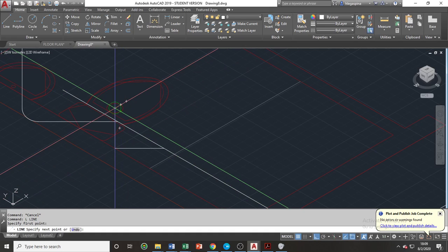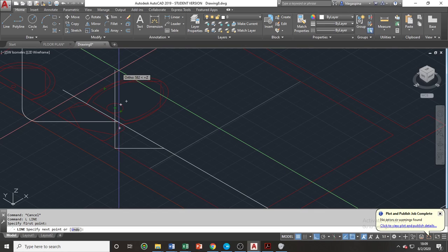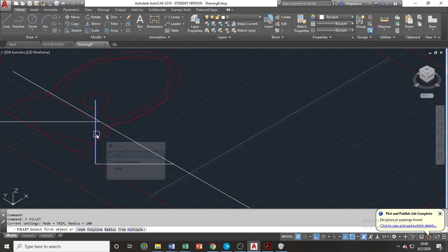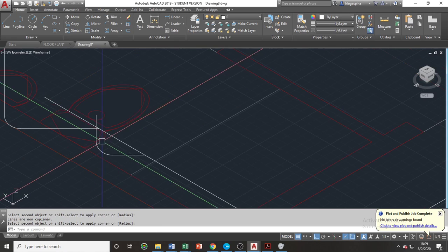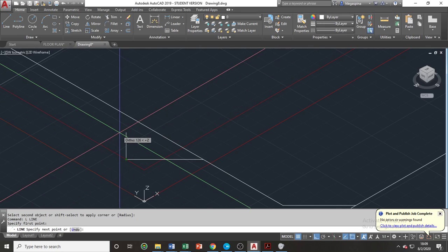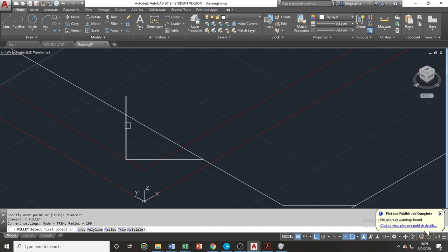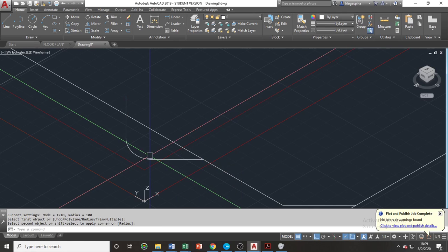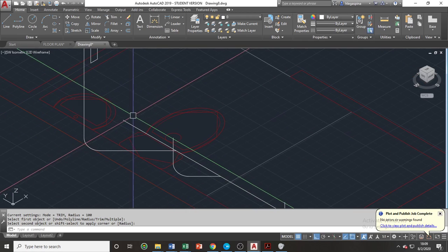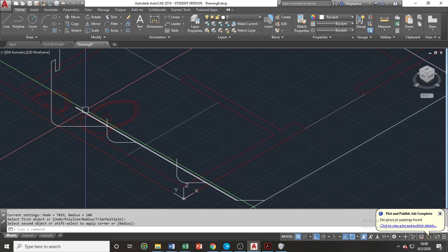Same with the water closet, they should be connected towards our water closet drain or water closet flange. And also, since there is an elbow underneath for these pipes, it should be emphasized using the fillet command. Same with our floor drain, another elbow. So we now have our drainage for the 3 plumbing fixtures.